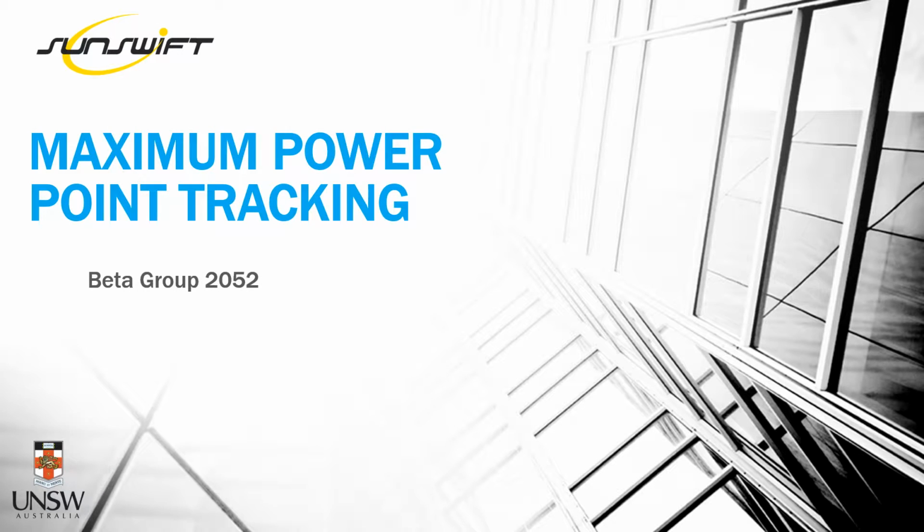A maximum power point tracker is a device which maximizes the power generated from photovoltaic cells. It can also be recognized as an electronic circuit that links solar arrays and the battery. Maximum power point trackers do this by finding the maximum power point located near the drop-off of an IV curve. The maximum power point tracker is necessary because it matches the relatively low voltage of a solar array and the high voltage of the battery.